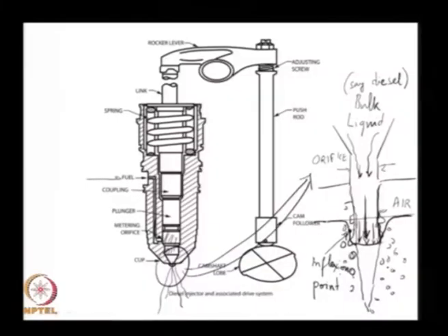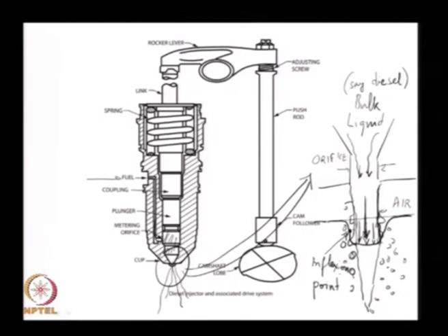Now, I pose the problem as though the air is atomizing the liquid, which is in fact the correct way to think of it, but really speaking, even if this liquid was injected into vacuum, the liquid by virtue of its own inertia also breaks up. But in a specific design that we are looking at here, which is a diesel injector, it is essentially a shear driven instability that causes these drops to be sheared from the surface area of the cylinder, where I get tiny drops.